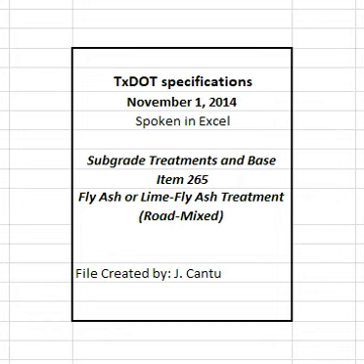5. Measurement. 5.1 Lime. When lime is furnished in trucks, the weight of lime will be determined on certified scales, or the contractor must provide a set of standard platform truck scales at a location approved by the engineer. Scales must conform to the requirements of Item 520, Weighing and Measuring Equipment. When lime is furnished in bags, each bag must indicate the manufacturer's certified weight. Bags varying more than 5% from that weight may be rejected. The average weight of bags in any shipment, as determined by weighing 10 bags taken at random, must be at least the manufacturer's certified weight.